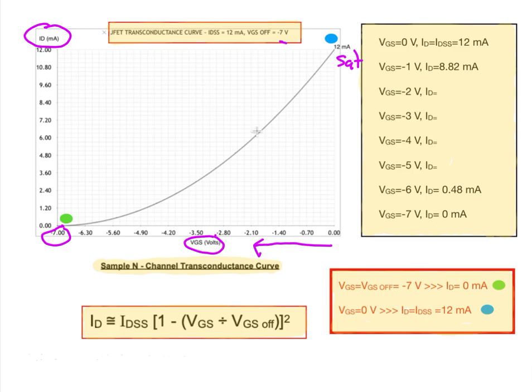So it's not linear. When they use this as an amplifier, they'll put the Q point somewhere in the area where it's approximately linear. So any JFET or MOSFET amplifier is going to be small signal, because as the Q point moves back and forth, we don't want to have a lot of distortion because it's inherently nonlinear. You don't have this problem with the BJT.